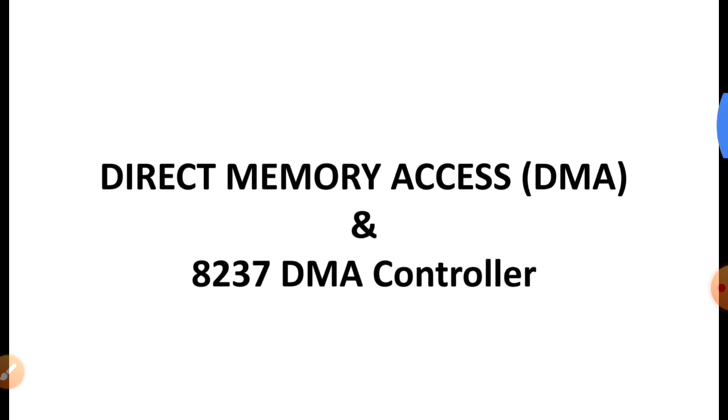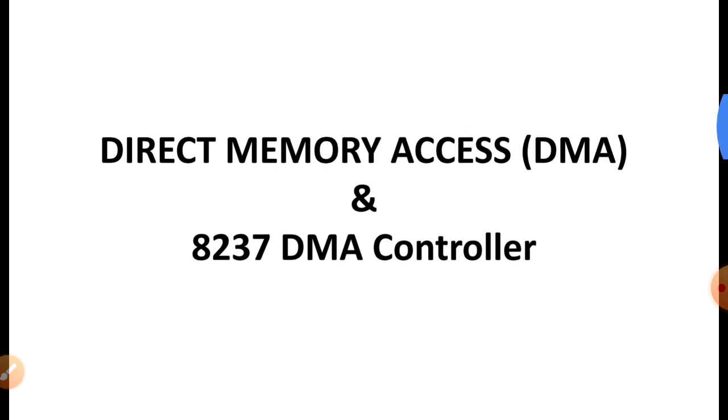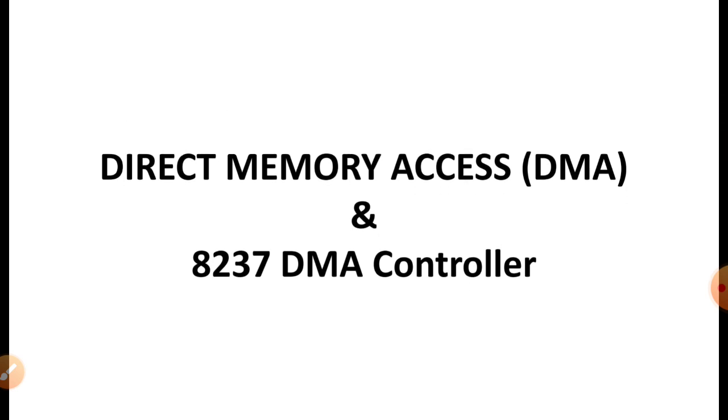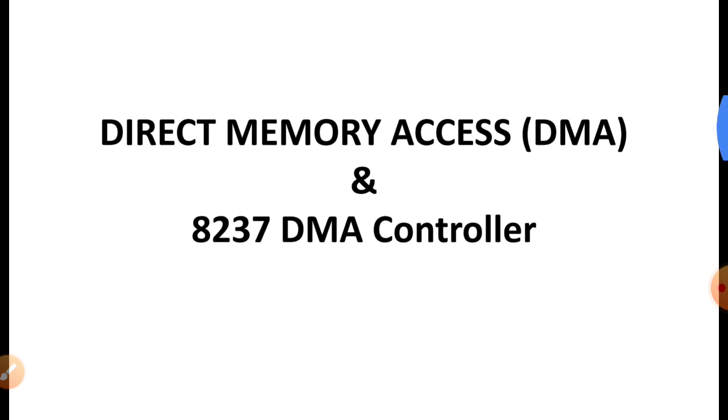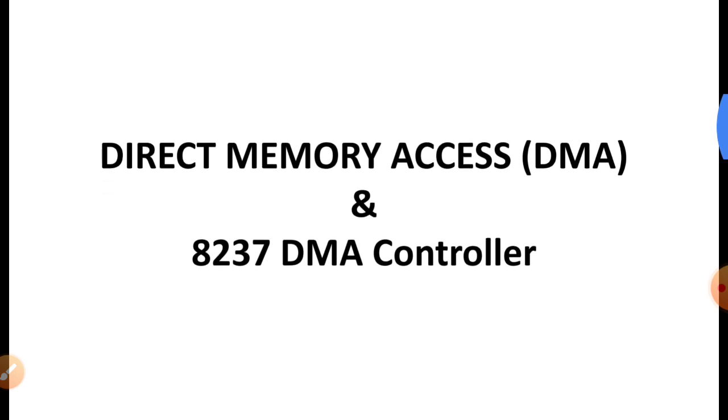processor to any one of the peripheral or memory devices, three important things are required: one, the address of the source; second, the address of the destination; third, the actual data which has to be transferred; and the fourth one is the control lines to do the data transfer work.